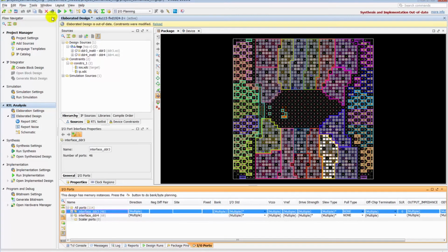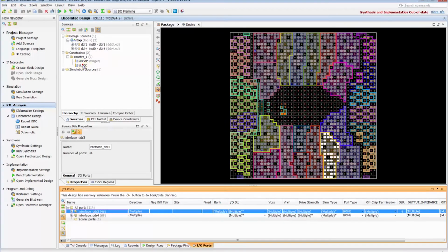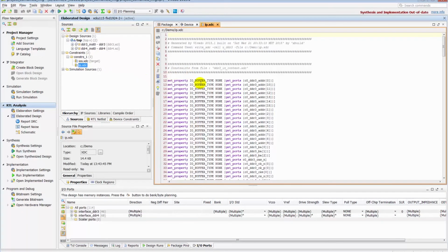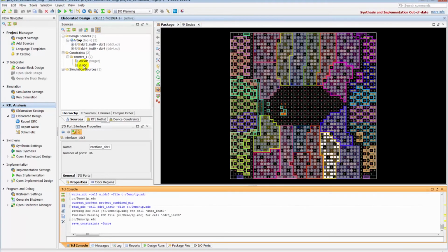And then when I use the save constraints command, it will migrate those module level port names up to whatever top level port names you have in your design. In this case, they happen to be the same because I used the same example design creation methods, but these ports could differ. They'll inherit the top level ports, and you're good to go.